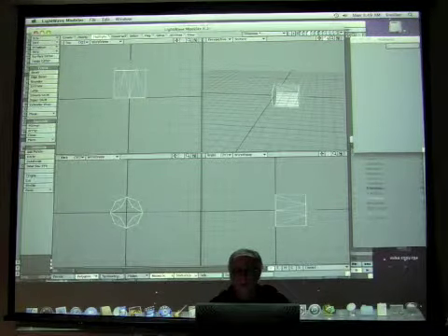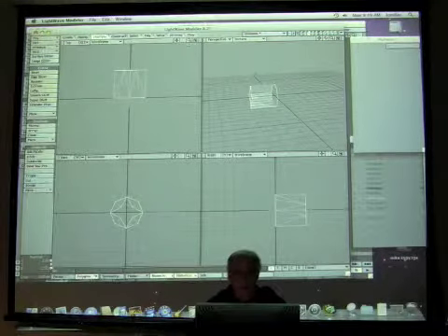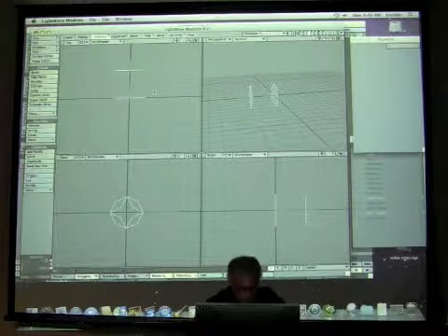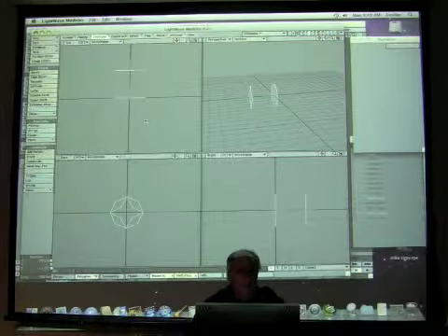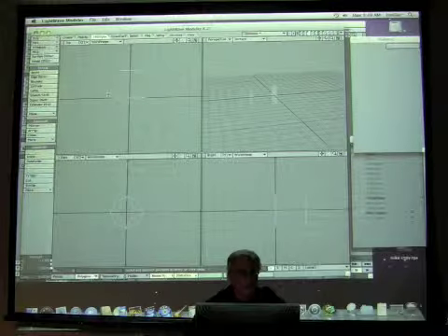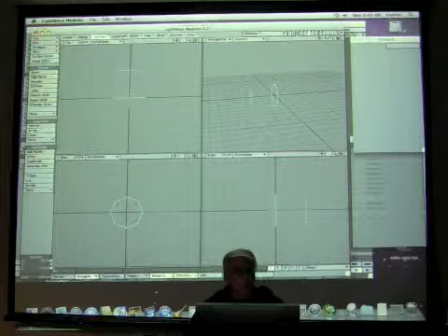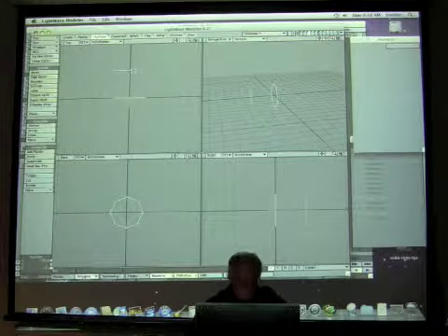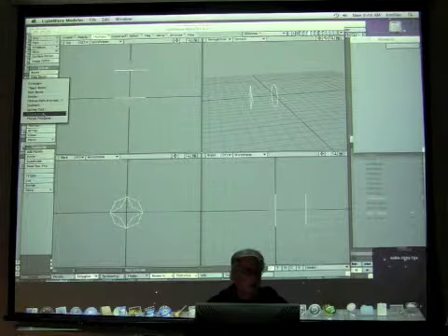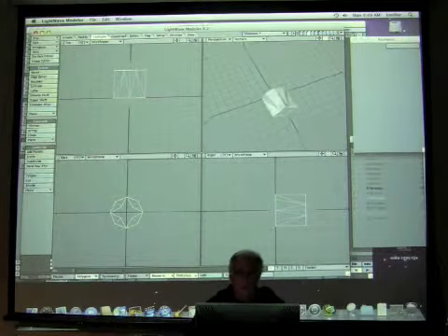And see how it's inside out? So I have to hit F for flip, and that didn't help me. So that's okay. I'm going to undo, and now I'm going to hit F for flip. Or better yet, what I need to do is take one of these and flip it, so each of these are facing outward. And now I select them. See how each are facing outward? And now I go here and select skin. And that works much better. See the shape you get with that?